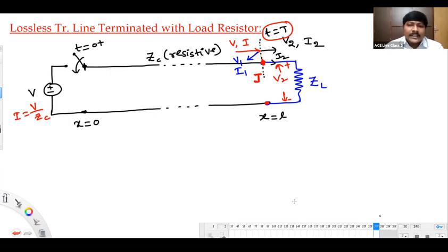2 times the V phase peak. You should take V phase peak, not V phase RMS. The maximum overcurrent value depends upon the fault analysis. That is discussed in fault analysis, which will give the maximum overcurrent, not in this transient study.